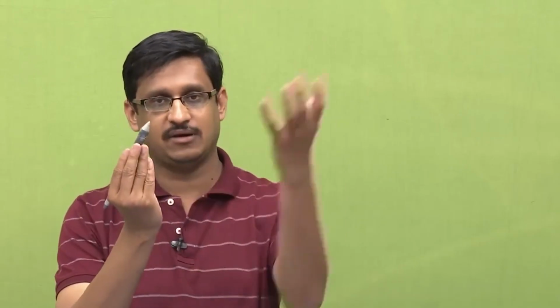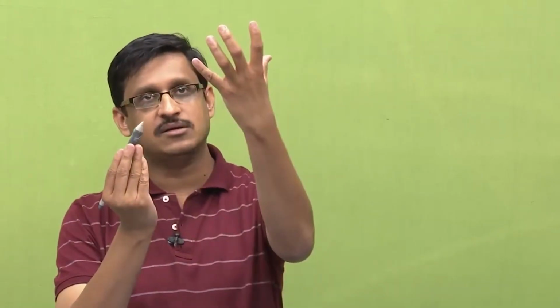So you have an antenna where currents are changing, and this changing current distribution creates a changing electric field and magnetic field which then radiates away. Now imagine that you are far away from the antenna and you have a receiving antenna there. The receiving antenna is pointed to the region where there are these radiating fields, and some of those fields can be intercepted by the receiving antenna and collected. In the region in between, there are no currents.